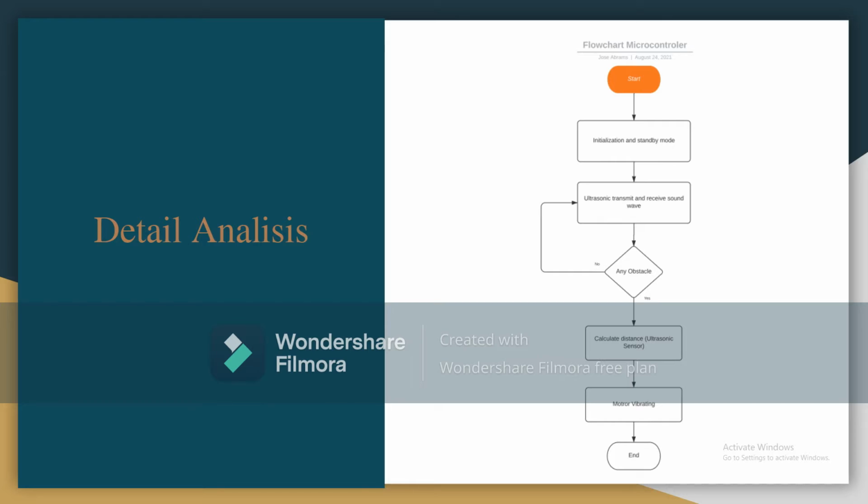We have a flowchart for the microcontroller. It starts off with its initiation in standard mode. Then we have the ultrasonic transmit and receive sound waves. In case that no sound wave is received, it should continue on a loop. If any obstacle is detected, the ultrasonic will calculate the distance. In case the transmission is sent, it's going to emit a signal to the vibrating motor, to the LED light, and to the buzzer to let the patient know that some obstacle is interfering with their way.